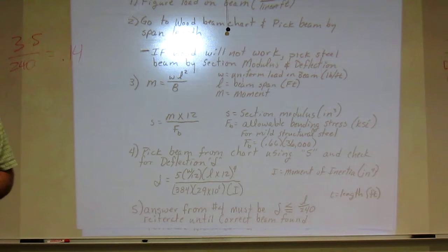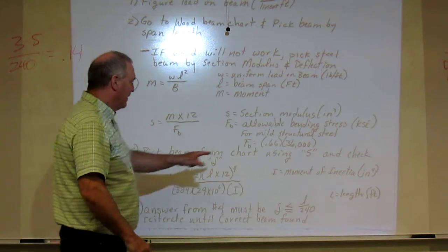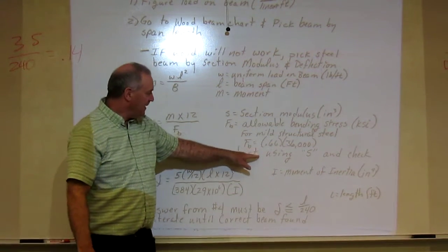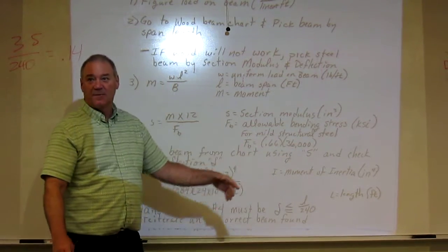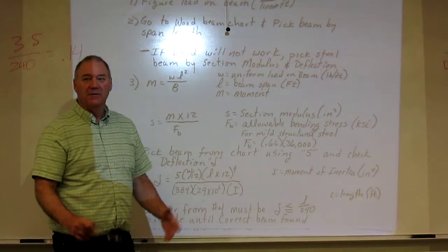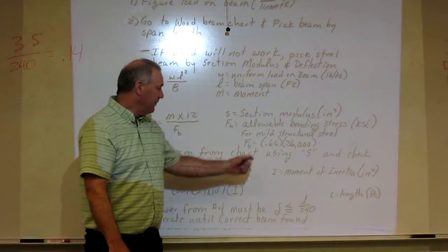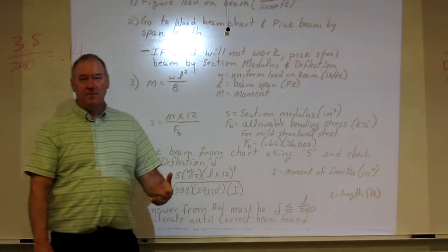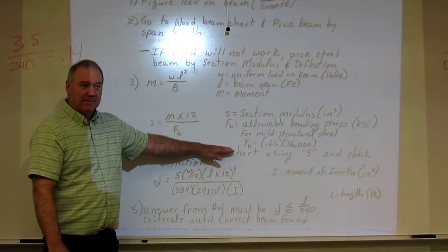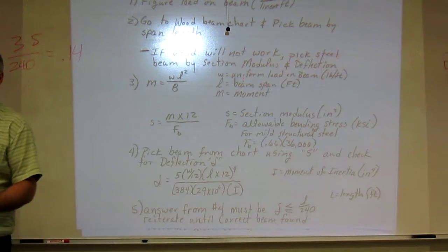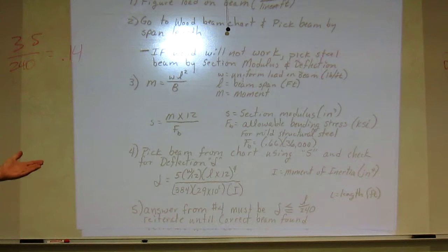You know what I kind of see by that? That's the F sub B. Yep, right here. Okay, so if I multiply it by greater than 1, I would be expanding the strength. I'm just multiplying it by less than 1, I'm reducing that strength. Can't use the whole strength of the beam. And the 2/3 is a constant. We use it with wood, we use it with strong, 60,000 PSI stuff, whatever we do. You always multiply the bending fiber stress by 2/3. That's why I make that statement. A beam should never fail under normal conditions, because we're saving 1/3 of the strength.